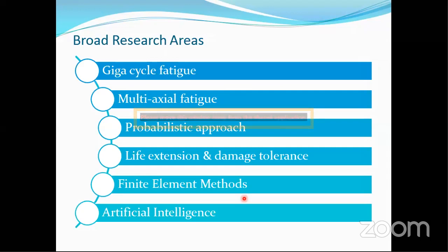So it consumes a lot of computational resources, and it becomes very difficult to simulate even a test crack. In that case, generally people go for 2D methods, but they don't take into consideration the thickness effects and 3D effects, but at least it will provide a conservative approach. Some methods like XFEM and mesh-free methods are continuously improving to provide good solutions, closer to the life of the component.